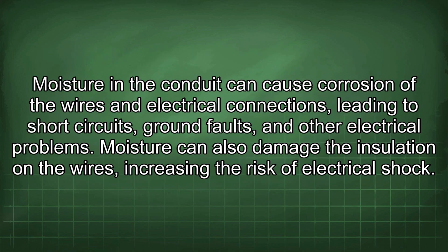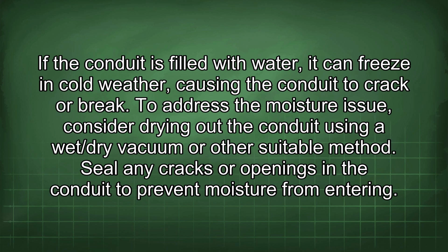Moisture in the conduit can cause corrosion of the wires and electrical connections, leading to short circuits, ground faults, and other electrical problems. Moisture can also damage the insulation on the wires, increasing the risk of electrical shock. If the conduit is filled with water, it can freeze in cold weather, causing the conduit to crack or break.